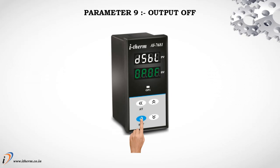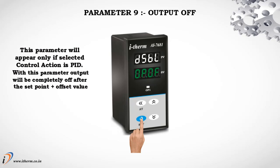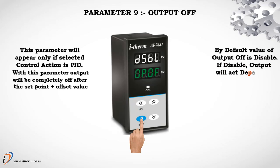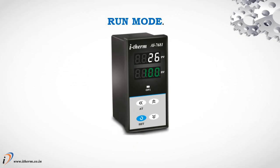Parameter 9, output off. This parameter will appear only if selected control action is PID. With this parameter, output will be completely off after the set point plus offset value. By default, value of output off is disable. If disable, output will act depending upon the PID value after set point achieved. This is the last parameter of control list. Press set key to enter in run mode.